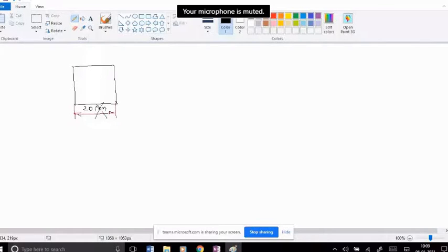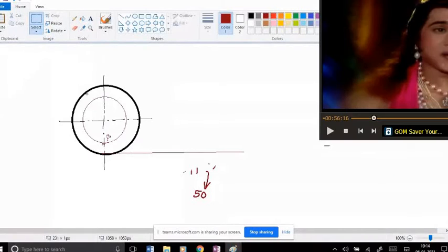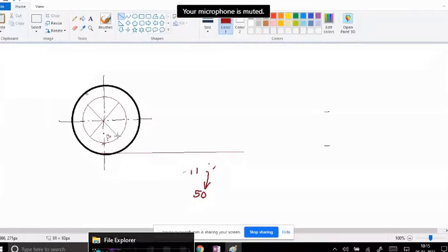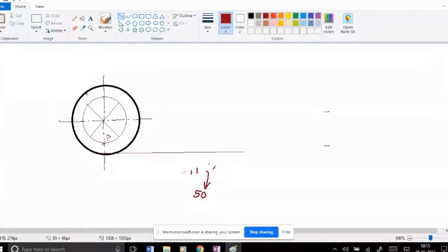Yes, sir. What you need to do is draw for half the distance, that means pi d by 2. So that is the distance. You need to draw the lines: divide the small circle into 8 parts, and draw horizontal lines from these divisions. Let me write this.